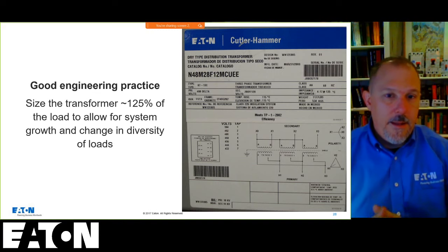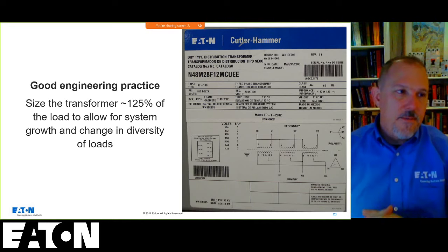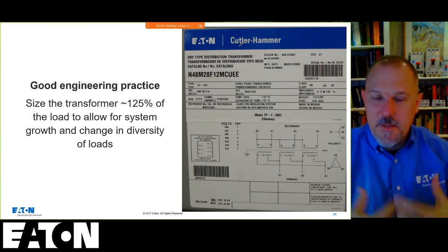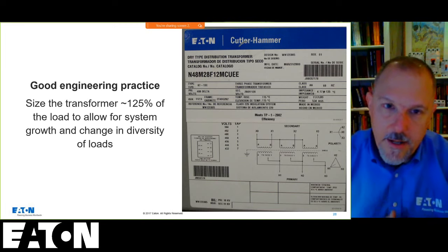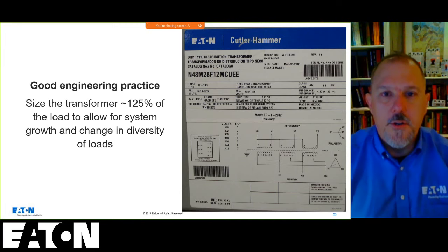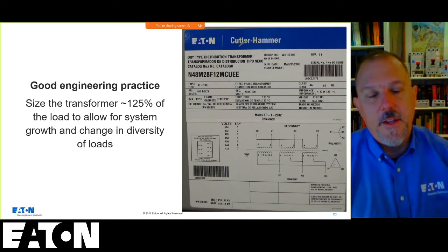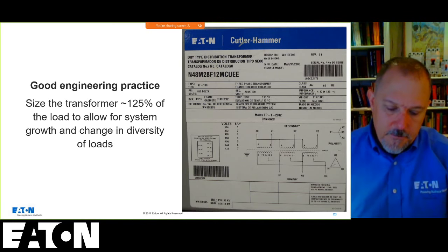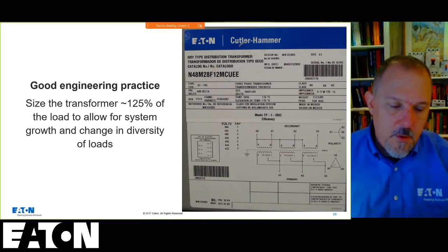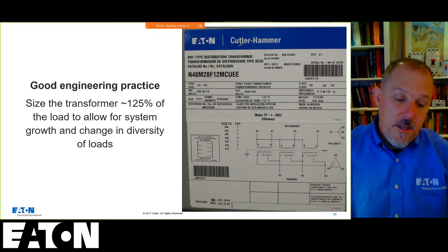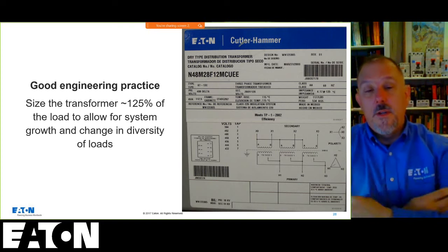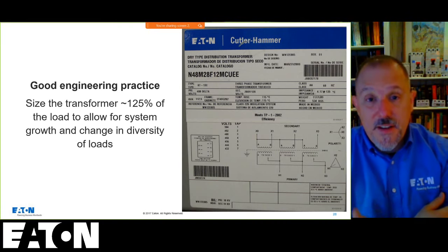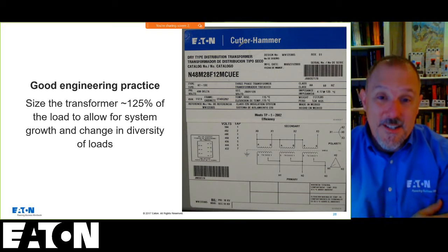So, I had a class one time, and I had a utility guy in the course, and he came up to me and he said, "Yeah, we do that." He said, we know they're not going to use whatever kVA they calculated because they have the analyses, and their usage is much less than the kVA of that transformer. And then he said the benefit of that is that they can reduce the conductor sizes, and so on.